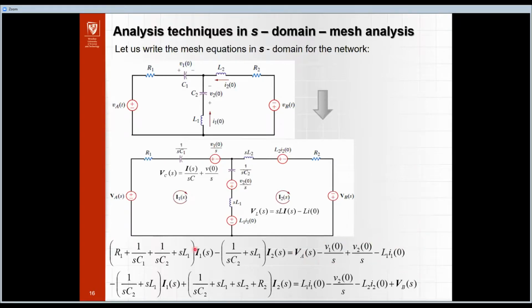On the right side of the equations we have the voltage sources. Of course, when we are planning to use mesh analysis, we don't substitute, instead of capacitors, the circuit with a capacitor and current source, because it is not convenient in mesh analysis. For mesh analysis, we use the S domain representation of elements with a voltage source. So here we have the voltage source connected with the first loop. We take into account the direction, and we obtain the first with the plus, and the rest minus.